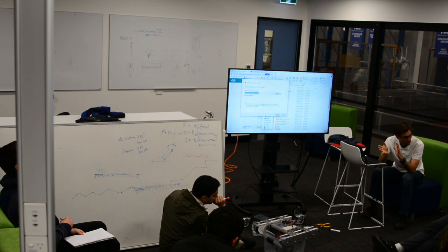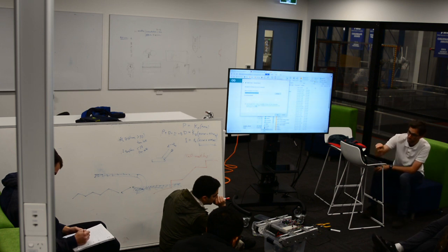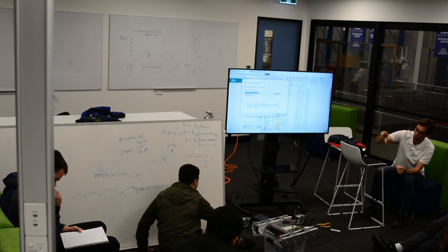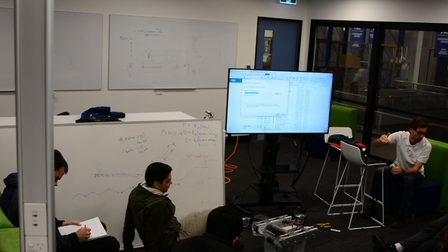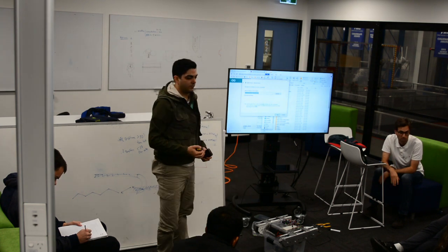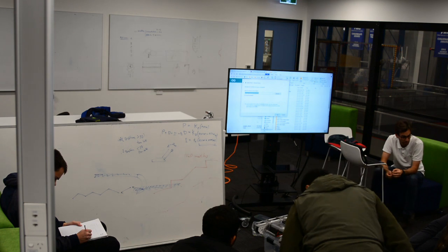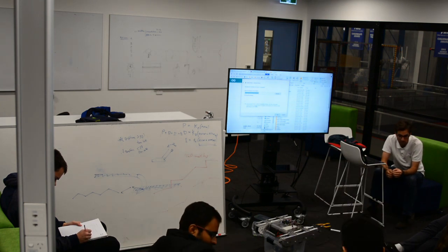You can have any sort of control rule you want, and it's not crazy to fiddle with these sorts of control rules. There are lots of custom controllers you can make. The idea of a proportional control with an offset to overcome that initial friction is a good example of a custom controller that's specific for this system that might work for you. But there's really any range of things you can try.